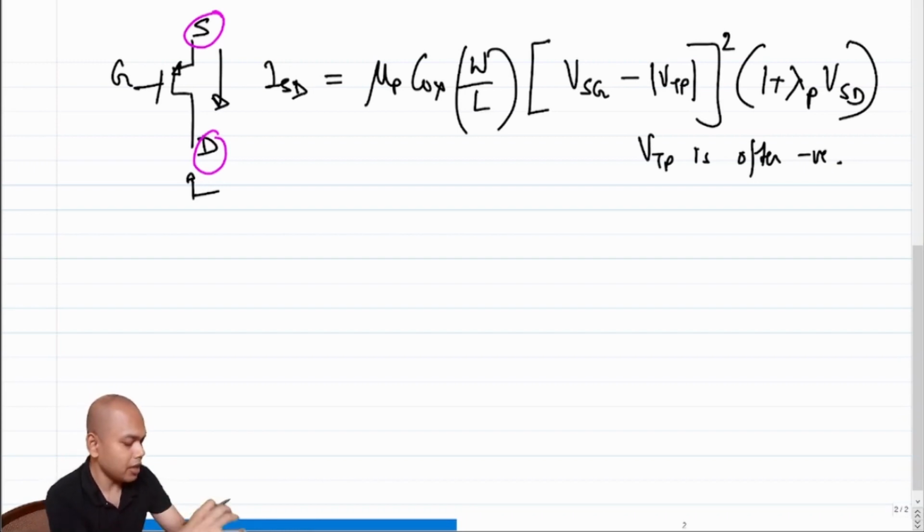And as long as we can keep the p-MOS transistor in saturation, then we can get a high enough RDS, which is independent of the quiescent drop across the source to drain voltage. And then we also analyzed the incremental equivalent of this structure.